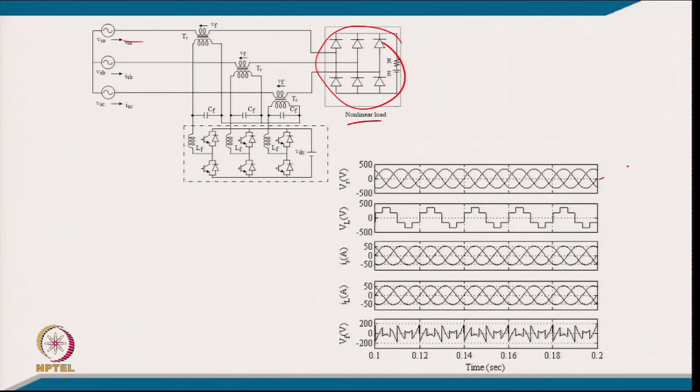The supply voltage is, let us say, a sine wave, a 3-phase balanced supply voltage. If we inject this kind of phase voltage, we will be able to force a continuous, sine wave supply current, and the same will be the load current at the PCC. The difference of these 2 voltages we have to inject. If we inject this voltage, then the current will automatically be forced to become balanced sinusoidal, and the current can be maintained in phase with the supply voltage. So, this series active filter is virtually working to eliminate the current harmonics of this voltage-fed kind of load. However, we call it a series active filter, which should really work to eliminate voltage harmonics, but here we are eliminating the current harmonics by injecting the appropriate voltage in series with the line.